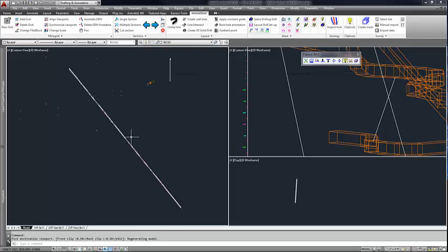Now I can go and make a plot of it. I can go in, I can do a section, manipulate a plate, make my wireframes, whatever I need from this point. So the clip tools are one tool that allow you to quickly maneuver and makes working in 3D and AutoCAD possible. Without that, AutoCAD is much more difficult to deal with in 3D. This is one of the tools that we have which makes it much more reasonable to work in 3D.